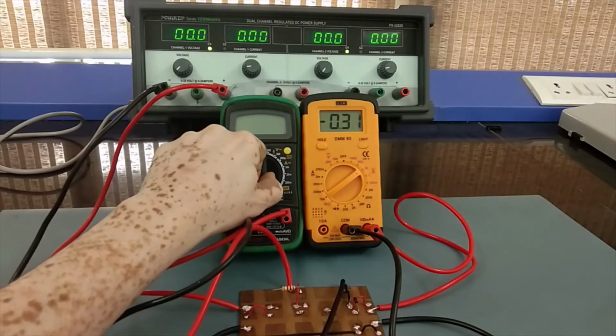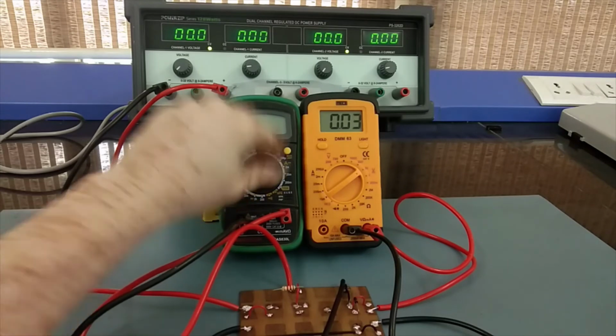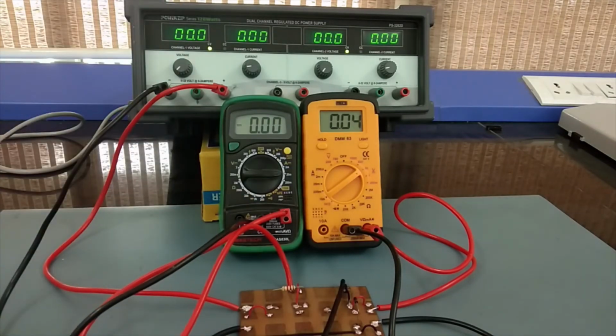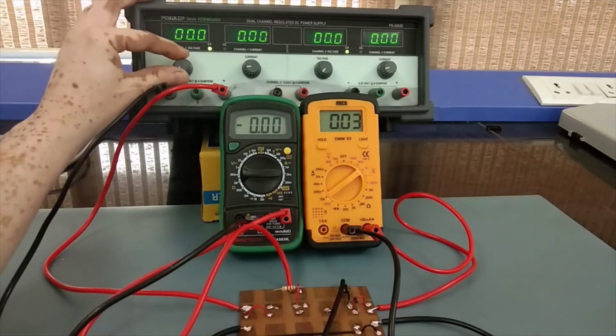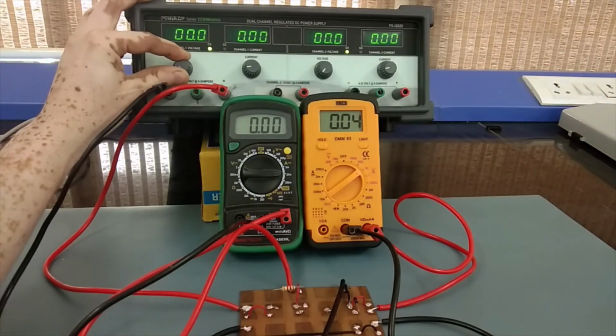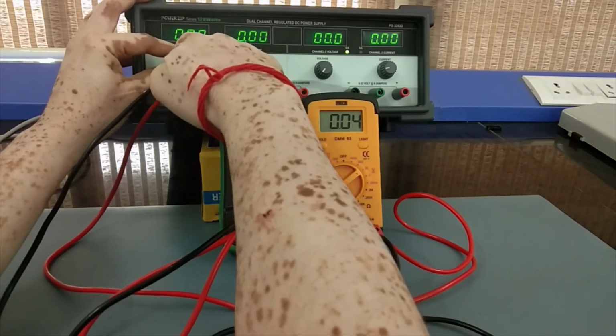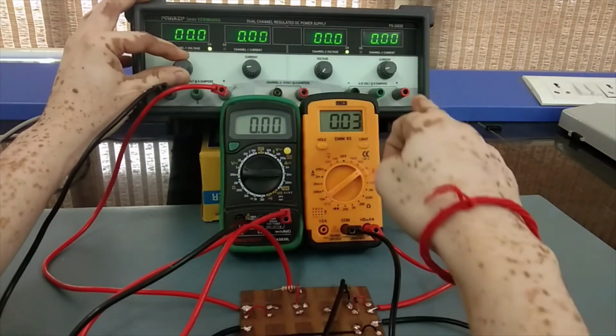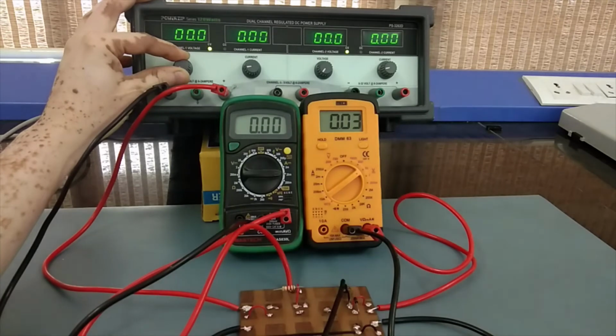I will be putting the current in the range of 20 milliampere, and here I will not keep on reading each and every value. I will wait for a while. If you are very interested, then you can note the readings so that you can plot a graph. I will not do that here. So I will increase the voltage. You have to look at this voltage. This I will increase, and you have to look at the voltage that is developed across the diode. Okay, so you see here, very slowly I have made it.